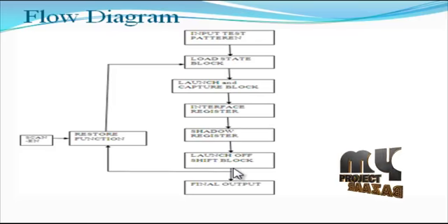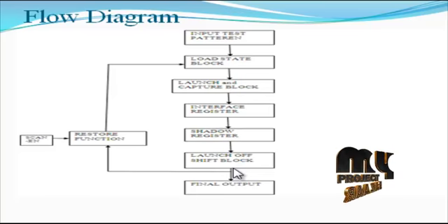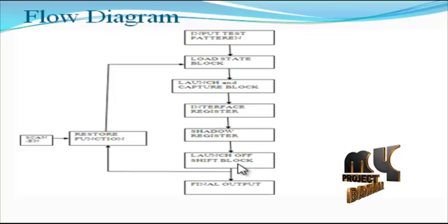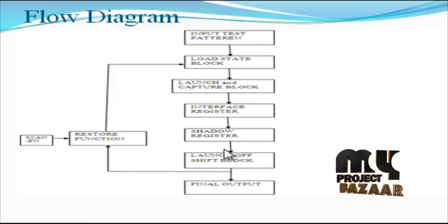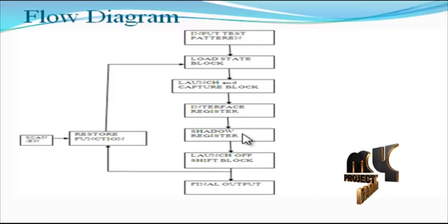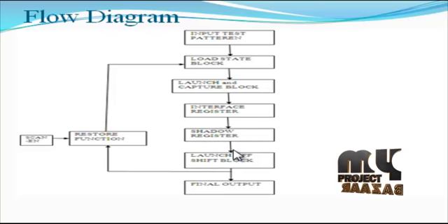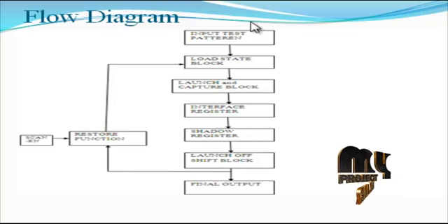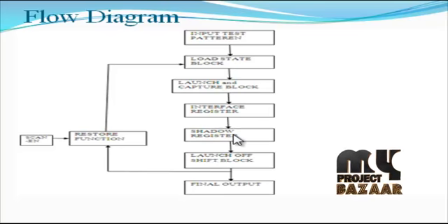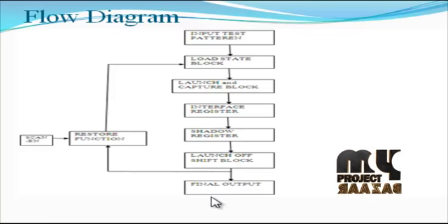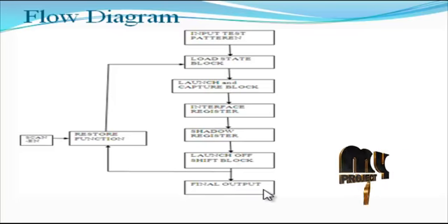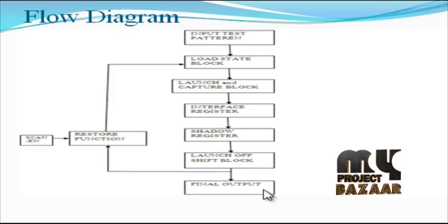This launch off shift operation is activated by the scan input signal. When the scan input signal is set, the launch off shift operation is processed. During the launch off shift operation, at the same time, the shadow register applies the last bit and compares it using the XOR gate function. Then the expected input is processed and the scan input is applied, so the two inputs are considered, and finally we calculate the fault detection process, and the output is calculated by the synthesis and simulation results processing.